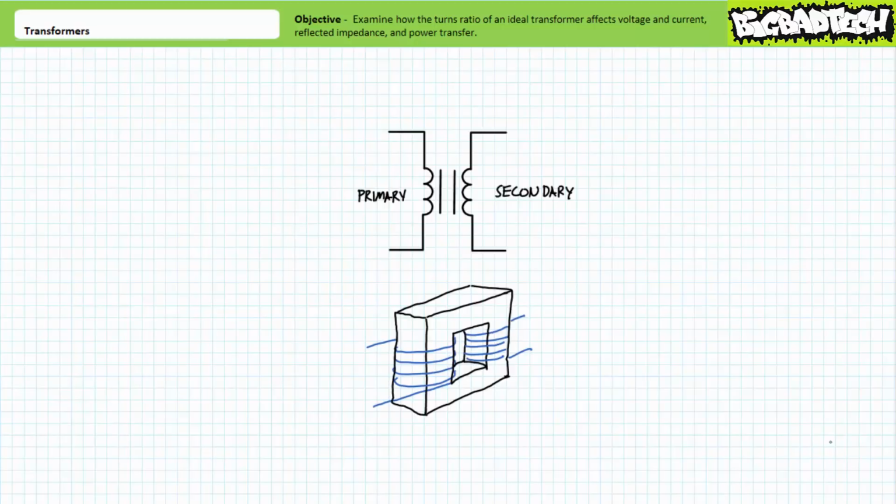It is for this reason that transformers ordinarily use an iron core, symbolized as a double bar between the primary and secondary windings. The iron core is substantially more magnetically permeable than air, up to 5,000 times for pure iron. This means that an iron core transformer is far more effective at concentrating the changing magnetic field linking the two windings.